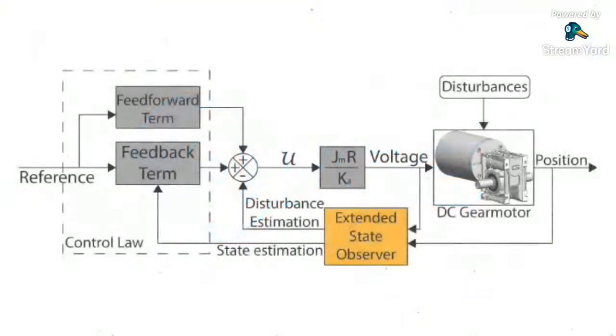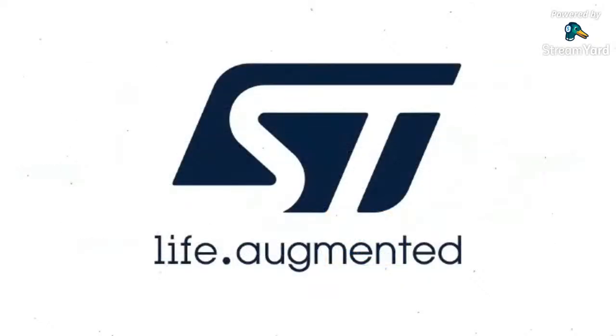Electrónica. This research presents the implementation of the angular position control of a DC motor using the active disturbance rejection control. This control strategy has the feature of compensating the internal and external disturbances. This is the block diagram for the control of angular position of a brushed permanent magnet DC gear motor. The implementation is performed in an ARM M4 microcontroller with floating point unit.